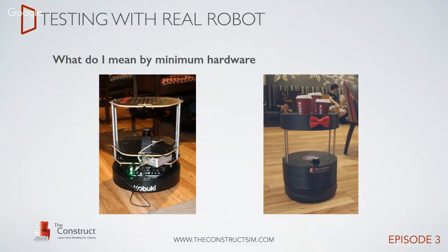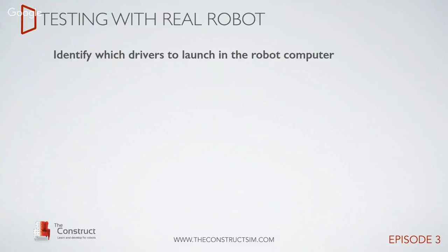So don't try to make your test with the final product. We are going to reach that point today here, but not yet. We are not yet there because many problems are going to appear when testing on the real robot. So it's a waste of time trying to do it on the final product. Okay, so use as little hardware as possible.